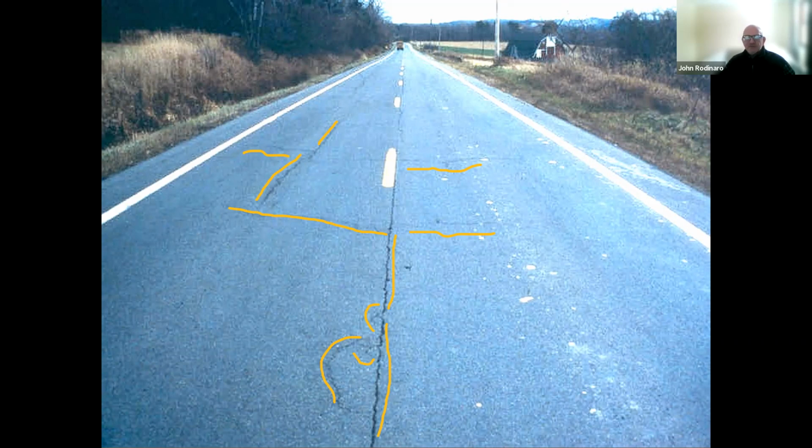You don't have a lot of interconnected secondary cracking. The cracks look like they're in good shape. The edges still look in pretty good condition. So this would still be a good candidate. However, as you're looking at the bottom of that slide, you're starting to get some secondary, interconnected cracking. That's going to quickly accelerate. You're going to start developing some potholes. So you need to get on this no later than the end of the season or early next season. Otherwise, it's going to have gone past its window for the crack sealing to be effective.